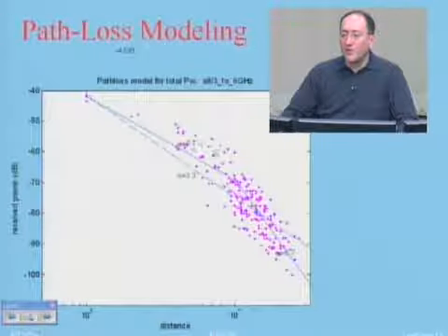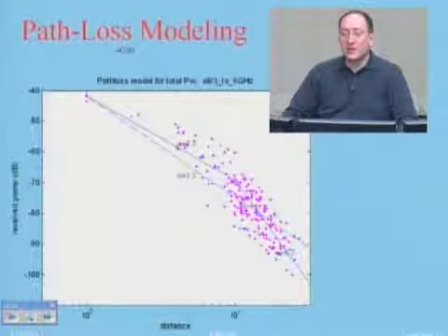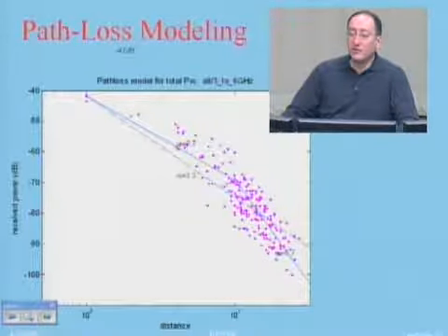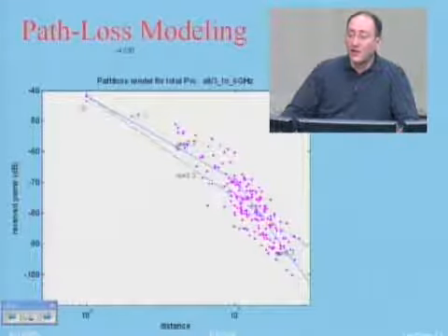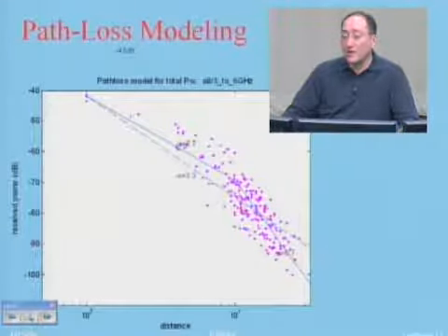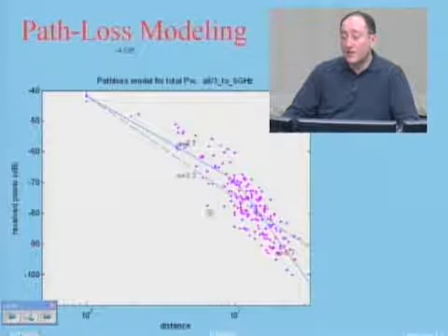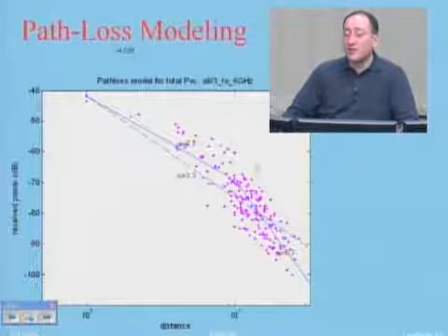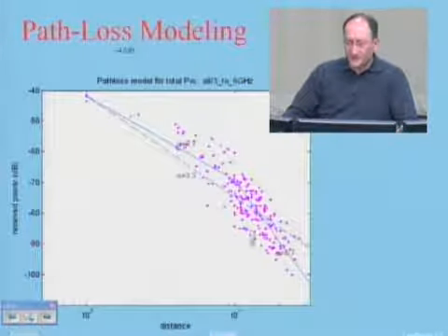So these are a bunch of received signal strengths from the multipath profiles, very similar to what you had in your project number 2. In project number 2, you fitted one line to that. If you fit one line, the distance power gradient is 3.3. These measurements are done in Atwater-Kent laboratories.